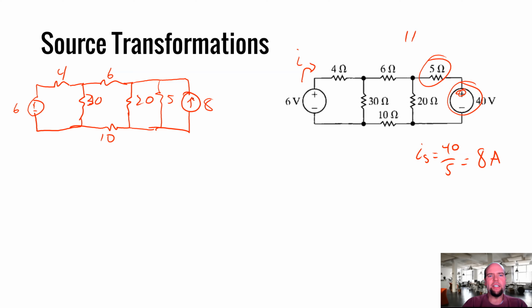And the other thing is, people might say, well, why'd you put the 5 on this side of the current supply? Well, it doesn't matter. These are parallel branches. We can switch the order of the branches, right? I mean, just imagine if you had this circuit physically in 3-dimensional space, you could just rotate the wires around and switch the direction. It doesn't matter what order things are in parallel. It doesn't matter what order things are in series. So we can switch them around.